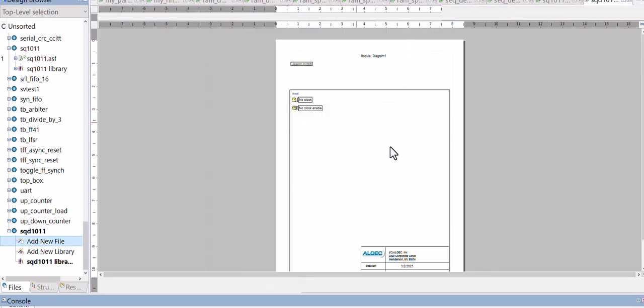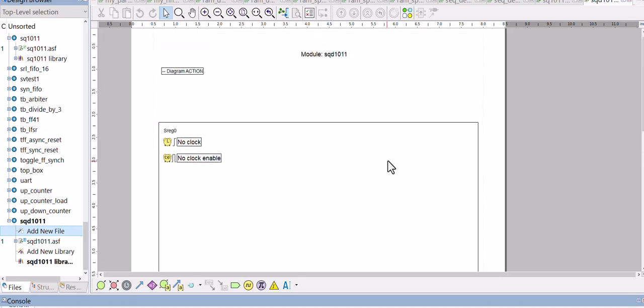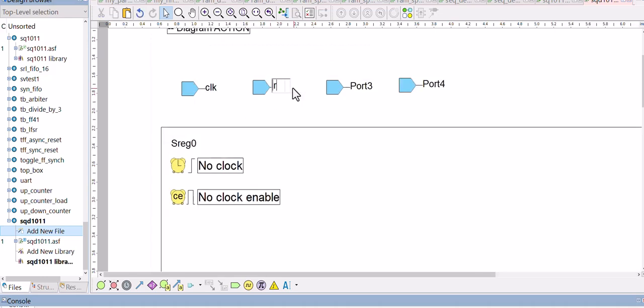It will pop up a template for the finite state drag and drop option. At the bottom there is one option for the drag and drop to add elements or items. So I just need some inputs: clock, reset, then D in and one D out. You can change the name like that: clock, RST, D in, D out. Okay, so I make this clock with this link.